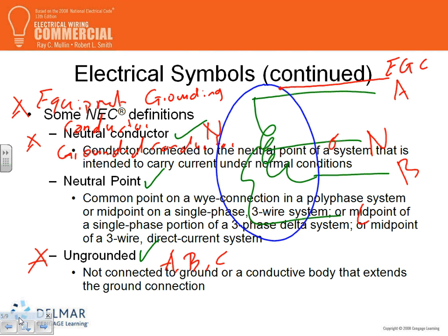If you're using conduit, it will drop this conductor for you. Very good advantage, right? No more copper. You don't need to pull another conductor with it. You can if you want to, but you don't need to, and it will save you money. If you ask me, even from an engineering point of view, it's counterproductive to pull a grounding conductor in EMT, unless you have like 500 runs of EMT, then that's a whole different story.